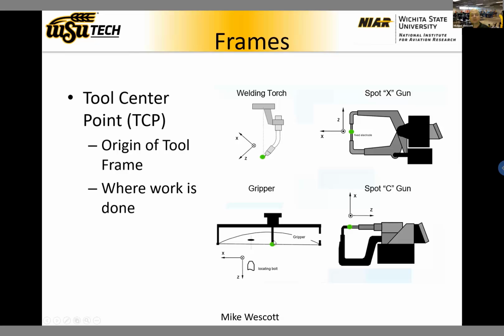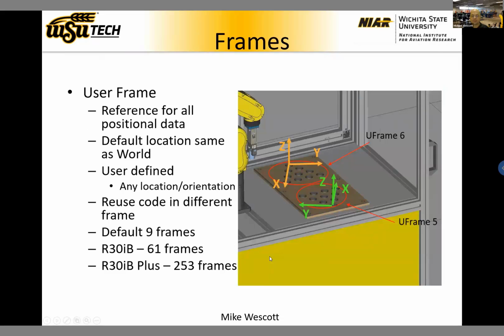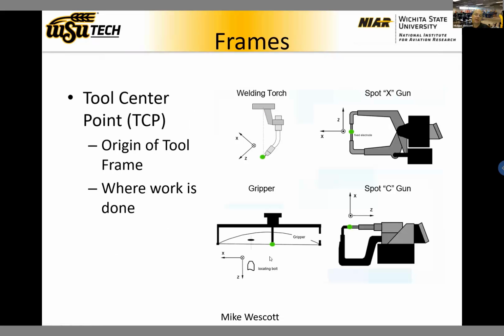This is a gripper example, a generic gripper. The center of your gripping force is going to be your tool center point, right? So in this case, the fingers would come together right underneath the tool flange, and your orientation in this case would not need to change. It'd be a direct translation, so you could use a 3-point method.